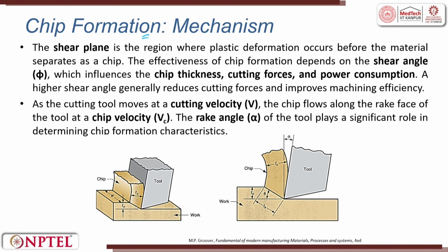The chip formation mechanism. The shear plane is the region where plastic deformation occurs before the material gets separated as chip. So, here is the shear plane. This is the shear plane. The shear plane is the region where there is a lot of plastic deformation. This plastic deformation allows the material to go further and form a chip which gets separated from the workpiece.